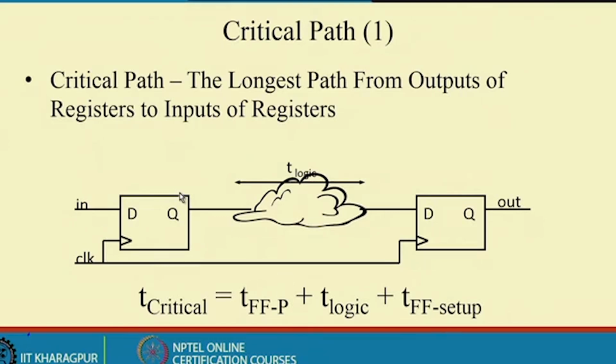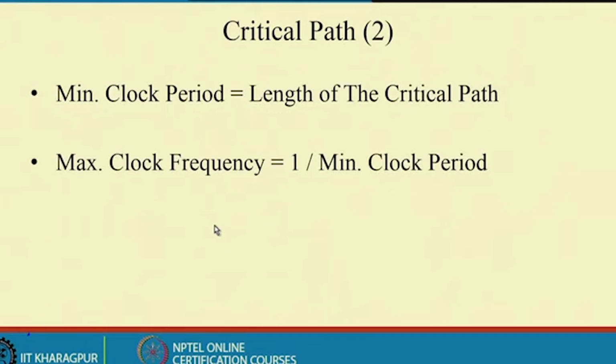So, what does it follow? This T critical then follows T flip flop plus the T logic, or the delay for these logic gates, and then the T flip flop setup time. Why do I need to consider the delay of this T flip flop setup, and the T flip flop of this particular circuit? We will come to that in a later slide.